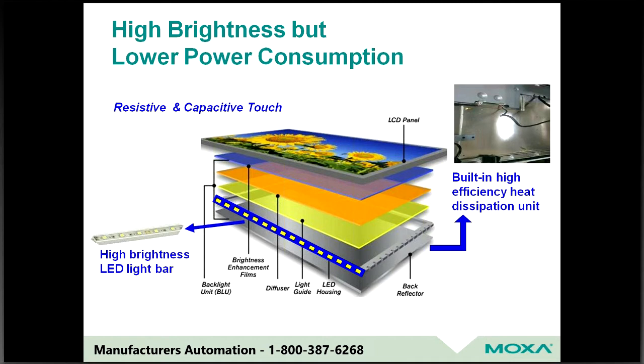Generally, we're going to have to shy away from capacitive, something that's similar to your iPhone or iPad, and go towards resistive, which uses some electromagnetic forces of the human body, but mainly it's force controlled. So you place your finger, for example, on one place on the screen. It takes that command, say, for example, it's a button, it's an operation. You click on, off. You push that with your index finger, it goes on and off. It doesn't matter if you have a glove on or if you have your bare hand, it will function, it will operate.